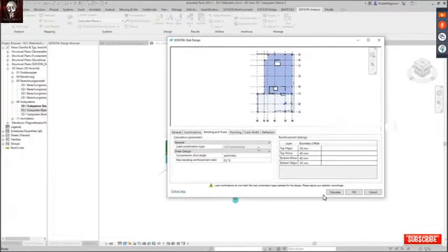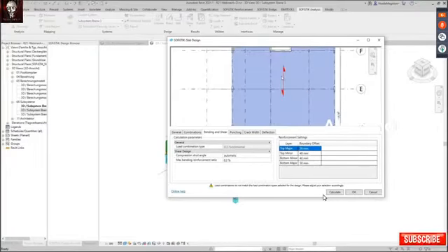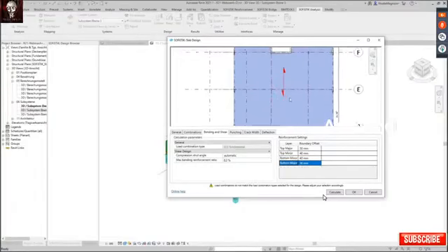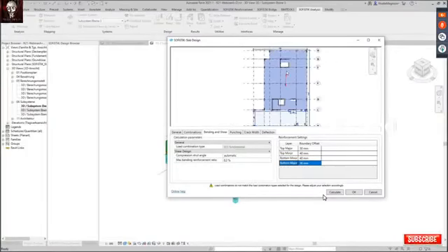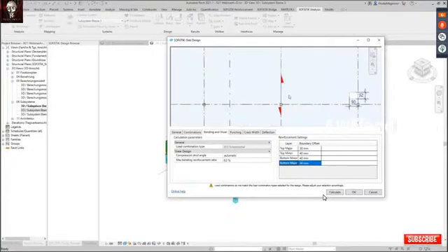The further tabs on the left are dealing with the design itself, with first the ultimate limit state design with bending and shear. Here you have some options which are new, especially the definition of maximum bending reinforcement. This option defines the distance between the different layers and the surface of the concrete. Here, I don't know if everybody knows about it. If you click on the line, you can see in the preview which direction is meant in the different slab elements.